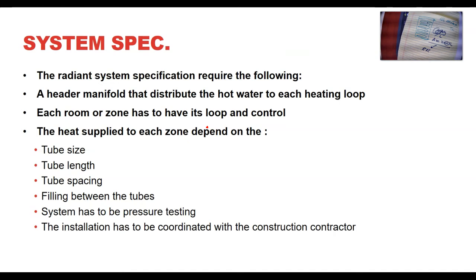So again, the system has to be pressure tested after it's done, and the installation has to be coordinated with the construction contractor before you put it in, because you don't want to install that and then somebody comes in and puts some holes or puts some carpet and punctures your system. And even before you run water into the system and commission it, you should have it tested thoroughly.